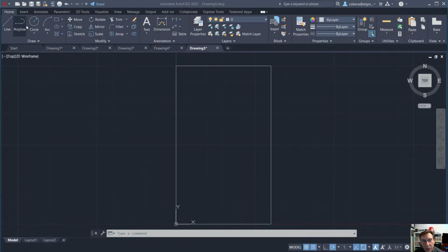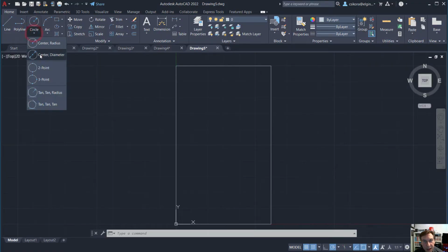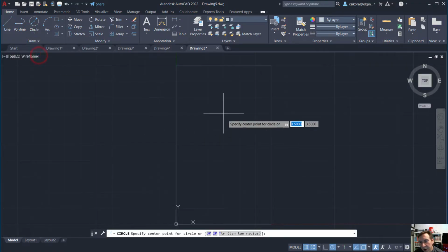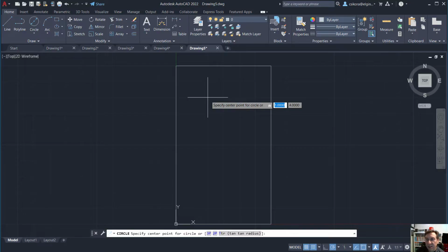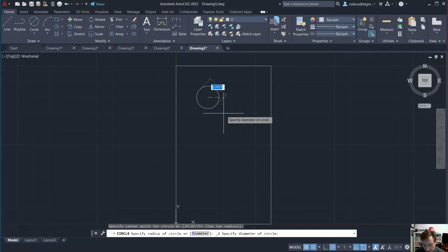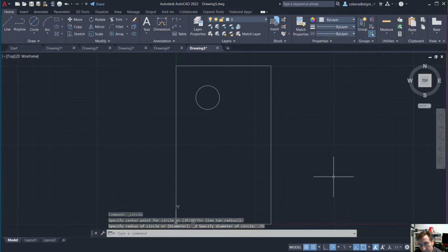All right, now let's go. We have that circle diameter given at 0.75, so make sure you select Center, Diameter, and locate this where it says 1 and 4. So for the X, we're at location 1 inch off the X and 4 inches on the Y. Go ahead and click and drag out a circle, type 0.75, and hit Enter. And that is the proper location we want.